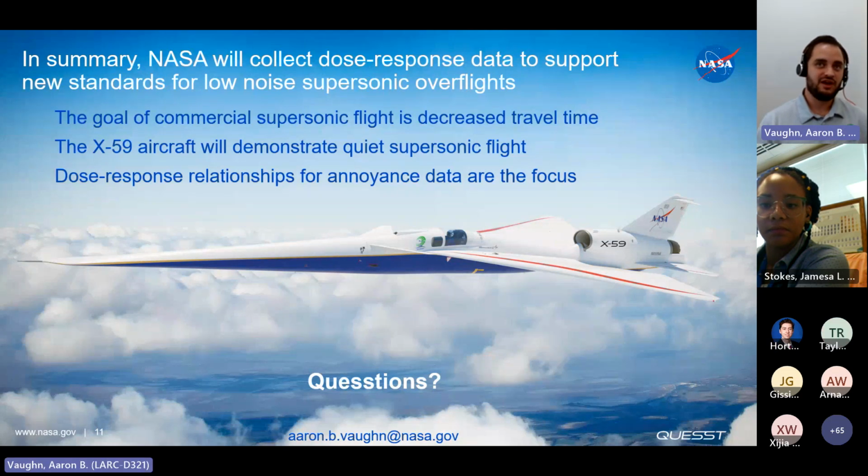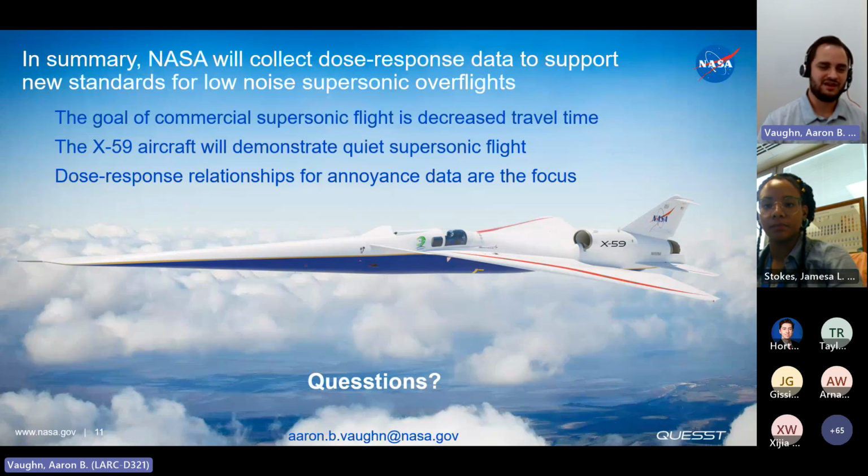Yeah, that's a great question. So the X-59 is designed to be at the levels that future aircraft that utilize this type of shaped boom technology should be at. So we will vary the levels. The current predictions are that the X-59 can produce about 70 dB to about 87 dB. The Concorde was 105. We're not going to fly an F-18 or another aircraft to reach those levels. One of the previous risk reduction studies did have the low boom dive maneuvers that got the lower range, but inadvertently, at the same time, supersonic overflights happened. So we had that full range from that data set.